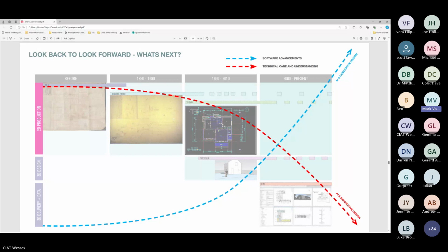People aren't then thinking that they need to check, well, what are the fire ratings? Are the fire ratings correct? Are the acoustic ratings correct? Have we got door protection? Are vision panels correct and in the correct locations? They're just relying on there being a door schedule that is pumped out of a Revit model.